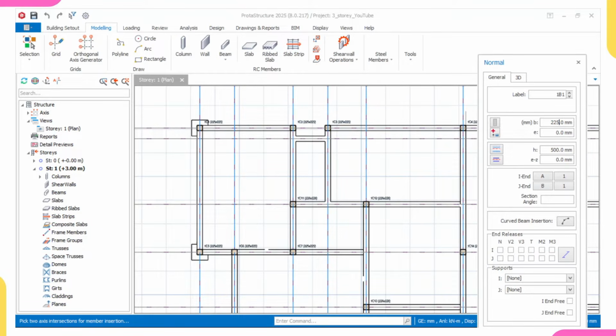But don't forget, we have 300 plus the slab, because we will place a slab on top of the beam. The slab depth is 150. So 300 plus 150 is 450. That's why we are using a depth of 450. Then if it fails, we'll increase the depth.